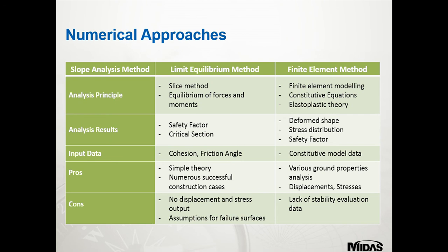So the cons, or the disadvantages, of the LEM is there's no output for displacement and stress in the soil. Importantly, before performing analysis, the failure surface has to be assumed, and for the FEM, the stability evaluation could be hard to interpret and requires experience of the engineer.